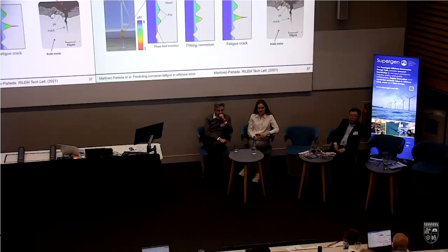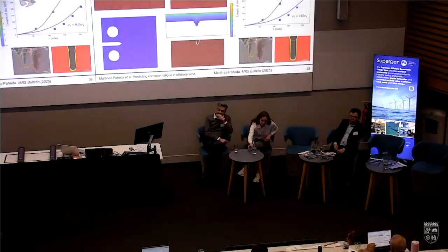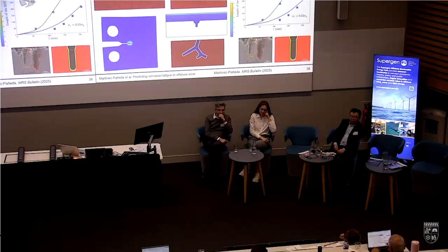The ability to simulate how this morphology, this corrosion front, evolves, and also the ability to simulate all these strongly coupled electromechanical phenomena. Because I said before, those pits grow driven by local chemistry and mechanics, but the local chemistry and mechanics themselves are very sensitive to the shape of those pits. And this new class of models is what we call phase-field models, corrosion fatigue phase-field models, or multi-physics phase-field models. And these are models that allow you to simulate how pits evolve, how fatigue cracks evolve in time, while simulating all the underlying electromechanical processes directly.